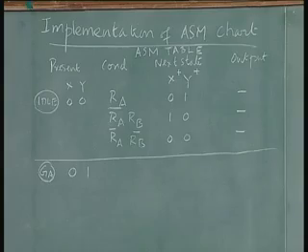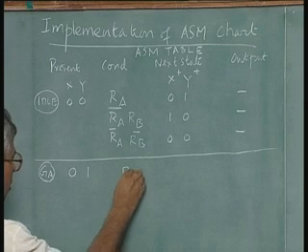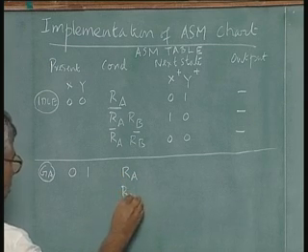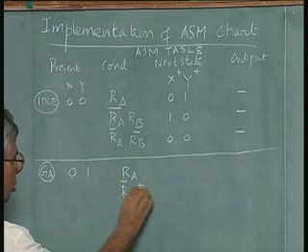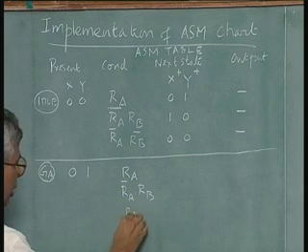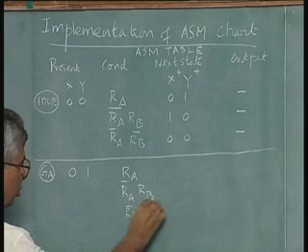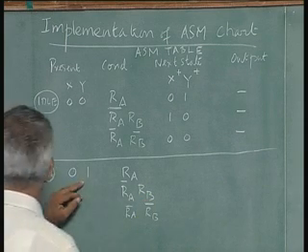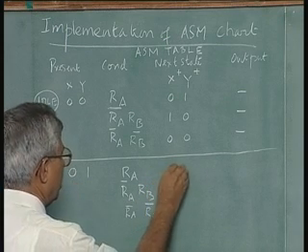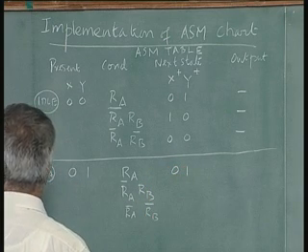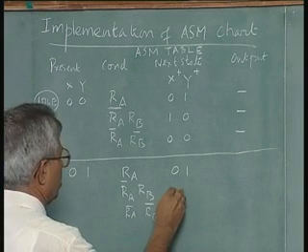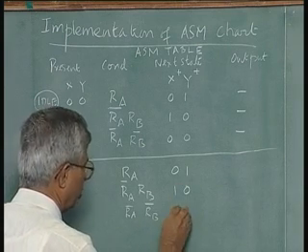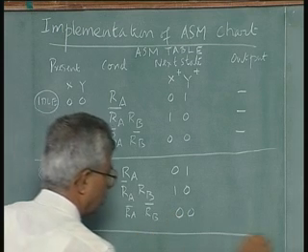So, first thing is RA true, second thing is RA false, RB true, third is RA, RB both false. In the first instance it goes back to GA, in the second instance it goes to GB which is 1 0, in the third instance it goes back to idle state which is 0 0. Completed the job.